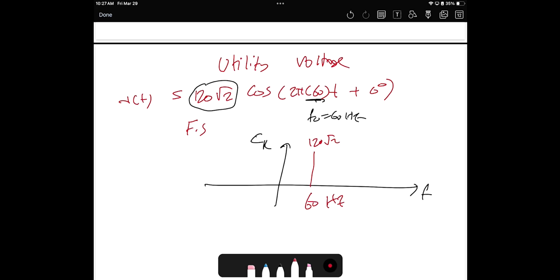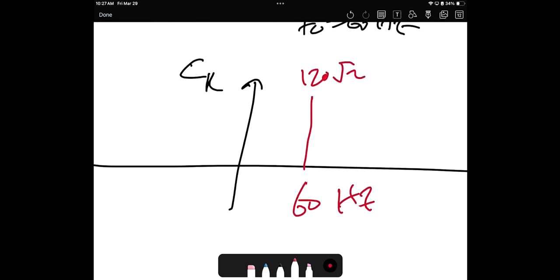When you do the spectrum analyzer, we have some oscilloscopes that can give the spectrum, or some devices that we have that can be a spectrum analyzer of the waveform. But when you do it on the device that you have in the lab, do you think you will get a pure signal like this? I don't think so. Why? Because the signal that we have is not 100% clean. It's not 100% 60 Hertz because there are some other equipment inside the system.